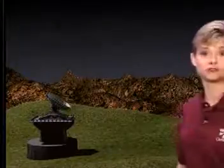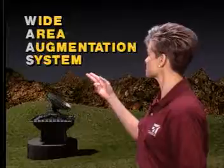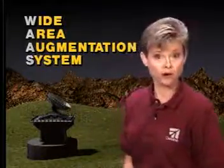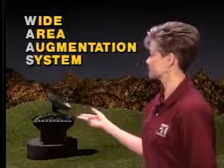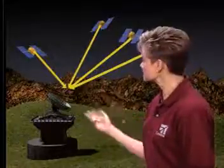One system to do just this is the Wide Area Augmentation System, or WAAS. WAAS is a network of over 20 ground stations around the U.S. which will receive GPS satellite transmissions. Since each ground station is in a known location, the locations derived from the satellite transmissions can be compared to this known location, and any errors can be identified.